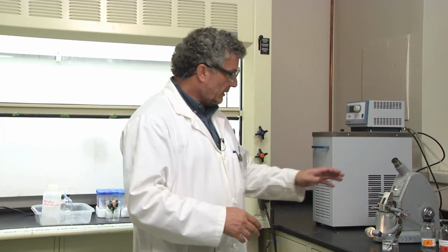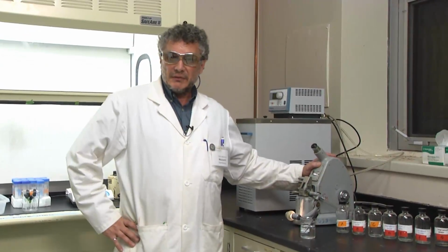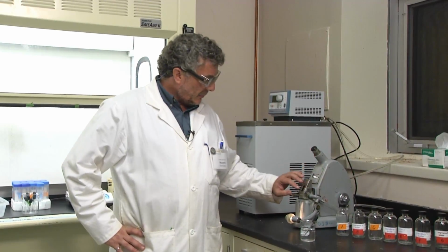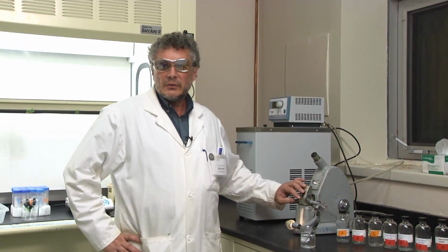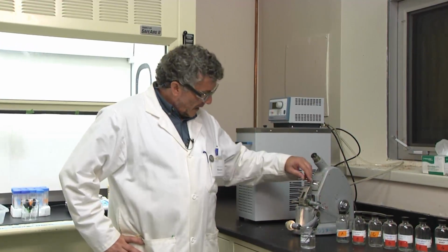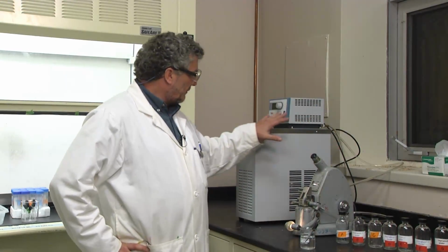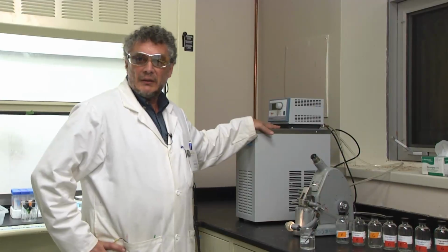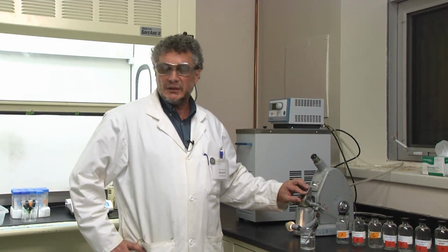The instrument that we're going to use to measure the refractive index, and from the refractive index to calculate the mole fraction, is an Abbe refractometer. These are extremely sensitive instruments that are designed by using sets of prisms that you can adjust to find the refractive index. So the refractometer now is connected through a set of hoses to this water bath, and the water bath keeps the temperature of the head of the refractometer at 20 degrees.